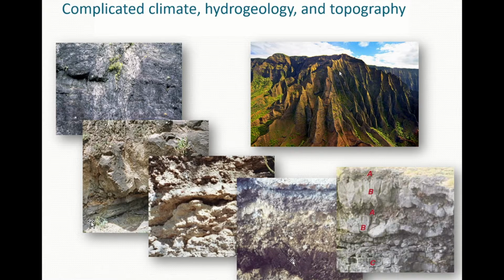As you can see here, the aquifer or ground surface is very steep. And this area is very difficult to access, and there is no data available here. So hydrogeology is very complicated by the lack of data and the suitability of models to deal with that. For example, models for sediment cannot work for a highly steep area like this. The limits are like 25%, while we have 100% slope.